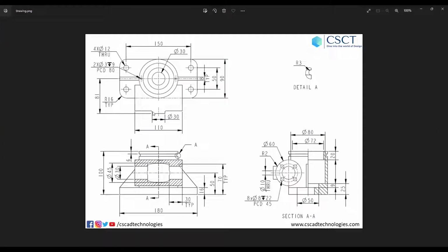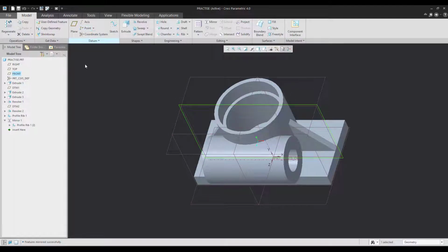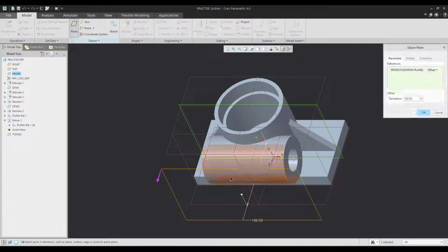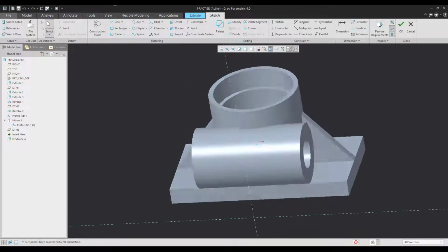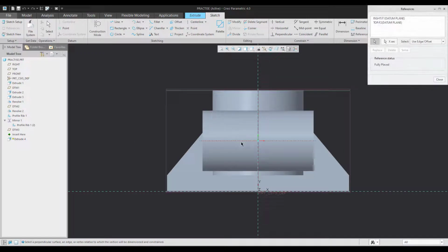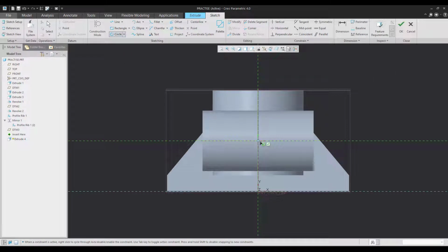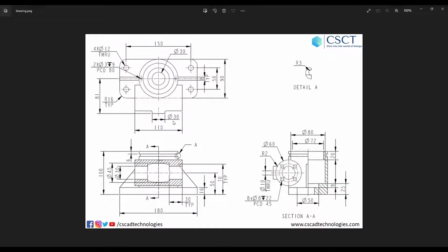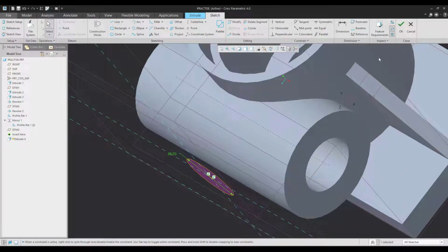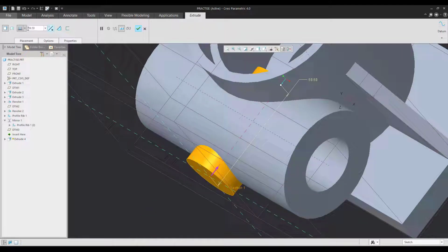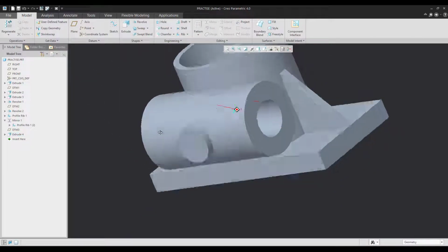Now, there is another addition of a 30 dia circle at a distance of 81. So as per that, I can take a plane at a distance of 81 and on this I can make the sketch. Now the feature is exactly at the center, so I'm not using many new references, I'm just taking the existing references, which is at 50 and the diameter is 30, which is provided here. Now the addition of material distance is not required because it has to be done up to the immediate next surface. So once you flip the body, it can be done up to the immediate next surface.